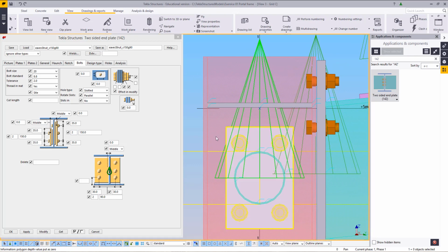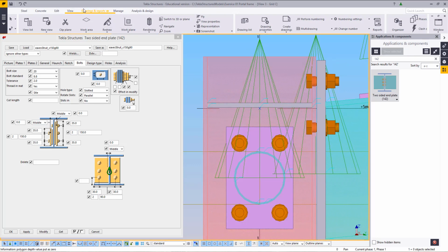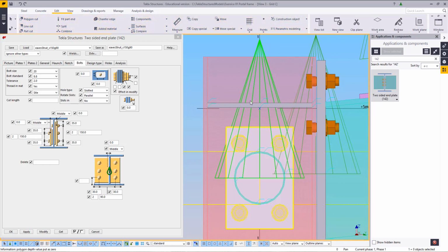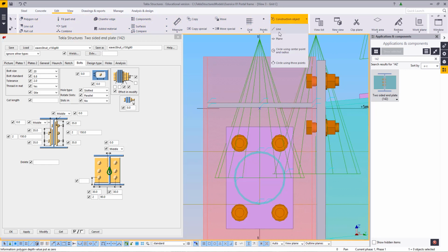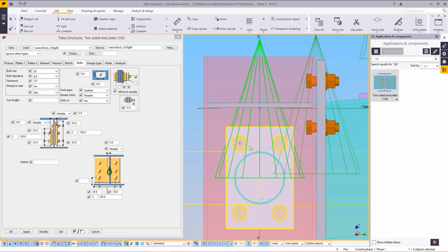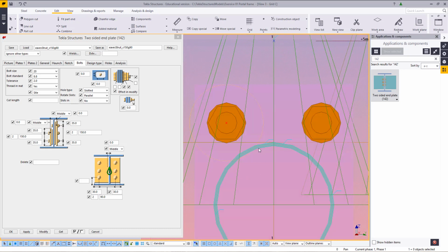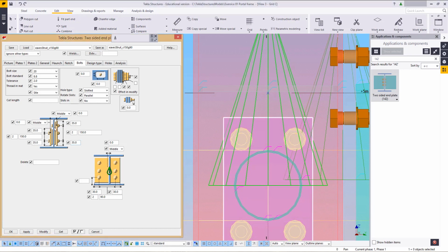Easy way to see if a pipe connection is correct, simply take your recommended edge distance on your bolt size, M20, so this is about 35. Draw a construction circle from the center of the bolt, 35. Let's use Shift and 2, and this will make it transparent and allow us to see. Now, as you can see, that circle is going through the pipe, and what that means is too small.